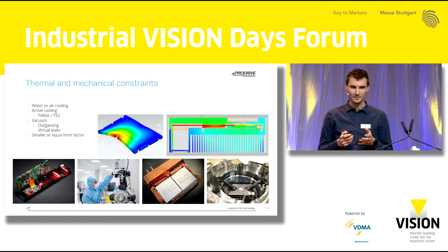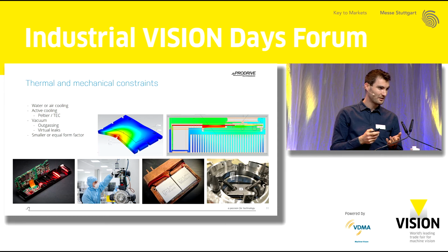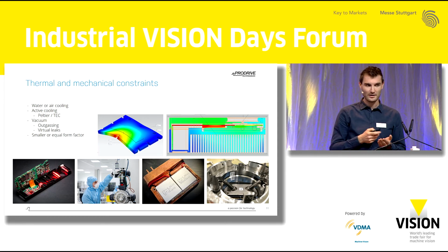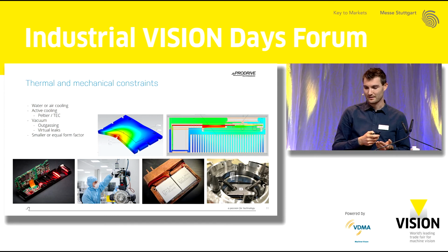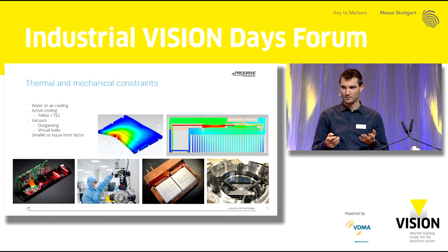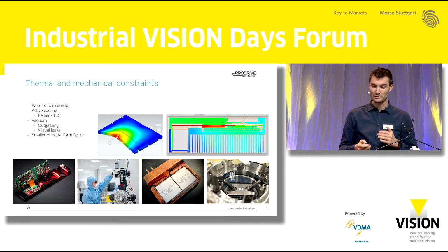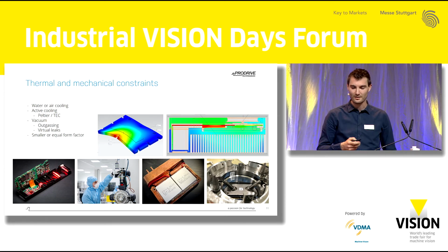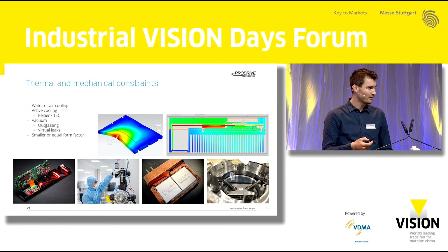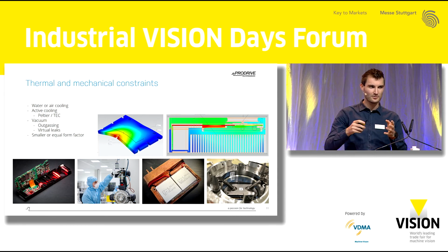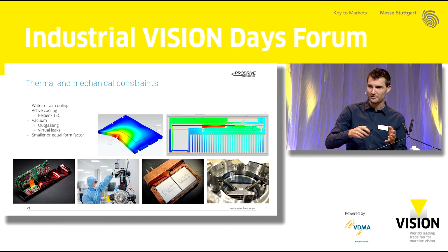And then for the vacuum, you can see there on the picture a vacuum setup to measure whether such a camera is vacuum tight. You need to do that with helium leak testing. And you need to also be careful with virtual leaks. And you potentially need to bake out some components to get rid of the outgassing of such components. You are restricted in some components inside the vacuum. So that's also one of the expertise that we got in the past years. And of course, all this within a small form factor, similar to the previous generation.